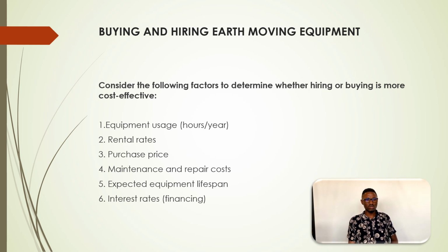For example, if the project is to take so many years, I would prefer buying than hiring, because if you hire it, at the end of the project you will realize that the cost of hiring will surpass the cost of buying. So I would opt for buying the equipment if I'm to use it for a long period of time. The other one is the rental rates. If the rental rates are so high, why would I rent other than buying the equipment?